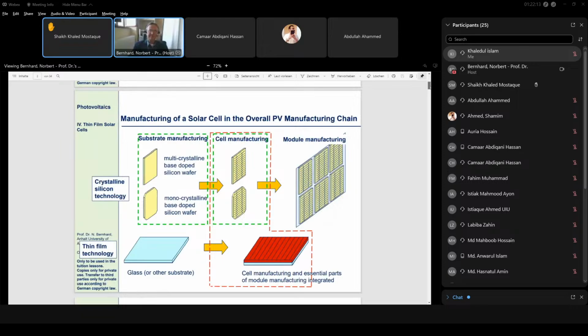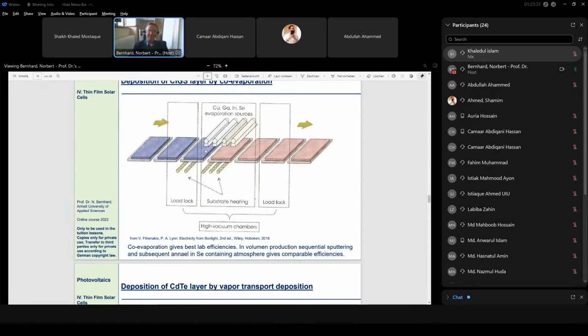Yes, so of course, this one is a vacuum process. I mean, this is a vacuum process, else it wouldn't work. Because in principle, of course, it forms these evaporation sources. I mean, to get a sufficiently high or fast film growth, you must have basically a molecular beam which is not scattered at some molecules, and therefore, of course, you really need a low pressure.